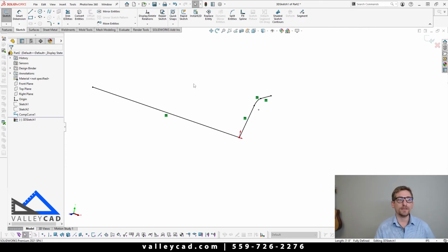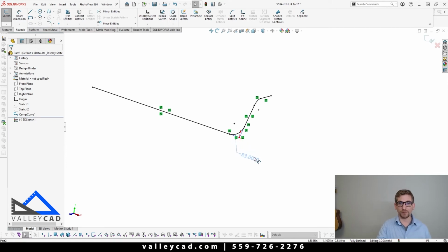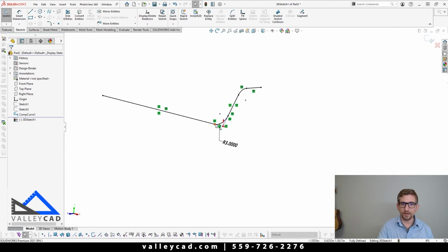And so now that we have a 3D sketch that I really didn't get lost in transition of trying to make, I can easily come in here, activate my sketch fillet command. With that selected, come in and specify the point that I need the radius added to, and simply say okay to that. So now as we look at my 3D sketch, you can see that I got a nice transition that's going along this horizontal line and it's transitioning up to that angled sketch that I had. And so sometimes you might have this if you are working with another drawing file that was provided to you and you're like, oh, I don't see geometry used to figure out this angle of attack or anything, but I do see this one side view.